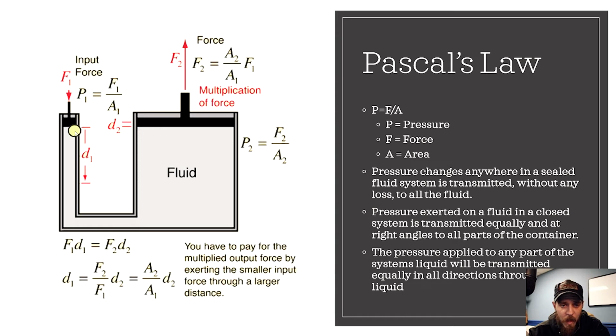If I'm exerting the same pressure here, because I retain the same force, I have the same area of the piston, and so I have a set pressure, we'll call it 100 psi, coming up here. All parts of the cylinder here and the piston seals are all under 100 psi worth of pressure. All right? Now, say I've got a little nick in the seal here. Well, that 100 psi is going to be shooting out here as well because it's enacting the same pressure on all parts of the system.